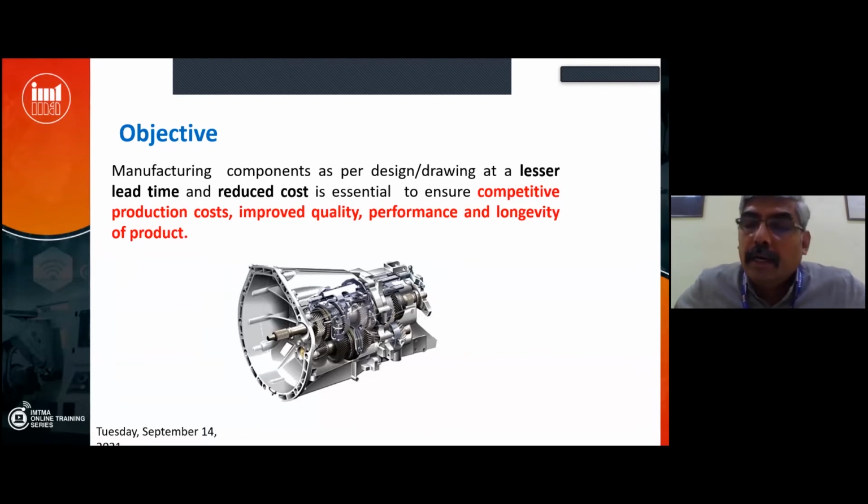Normally, whenever you get a new drawing for a development, what happens? You have to study the drawing, list all the critical dimensions, GD&Ts, then how I can hold it, where I can hold it, then how much finishing allowance I have to give. All those things will take time. And next, you have to select the right tools for that. Sometimes you'll have an undercut in the corner, sometimes an undercut in the OD, and there will be some critical things, either bore size or something like that. See, at that time, any wrong selection leads to your lead time increasing.